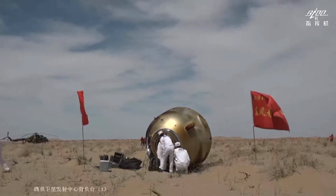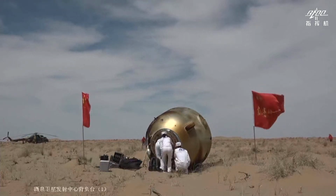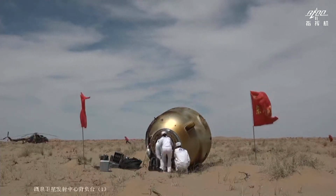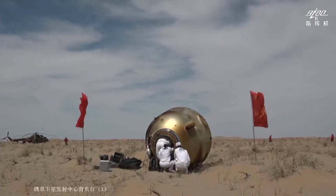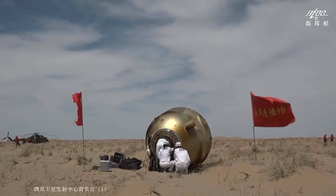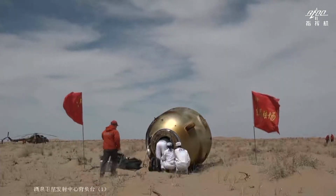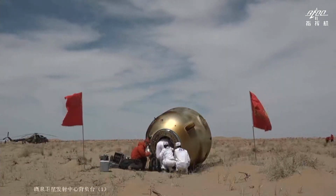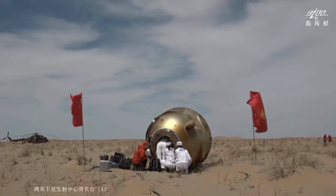So this is the reason why we chose the eastern part, because theoretically speaking, every day we have a window to conduct the recovery. But for every day the trajectory will be different, the orbital plane of the space station will be different compared with the landing site. So every day we have a possibility to conduct a landing, but every day it will be a little bit different.